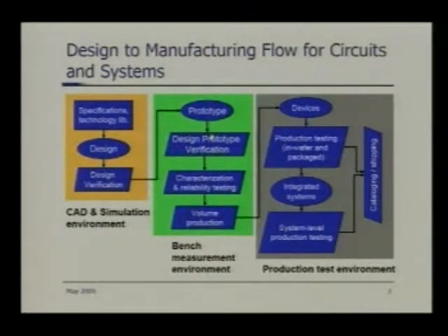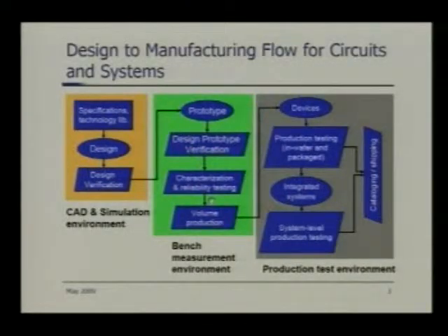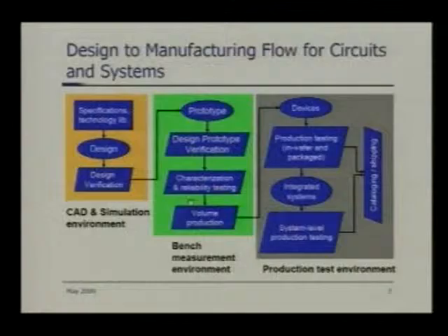So you have the test fixture, you apply the test signal, you measure the test response, and you try to do the design prototype verification. That brings us to the next thing, the characterization and reliability testing. Just verifying some of the specification is not good enough. You have to verify the specification over the VCC, over the temperature, over all the process corners. Then only you are done with the characterization.